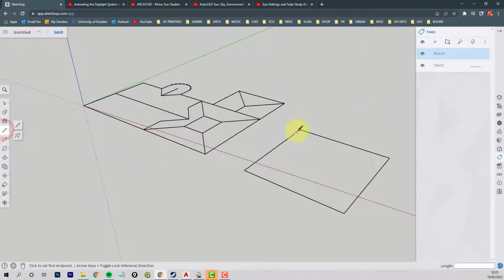Okay, I'm just going to trace around what we've got. I don't want it to snap onto SketchUp's own axes, so you can use the Alt key to stop it doing that. You don't have to hold it, you just have to press it. So you see there it says linear referencing all off. So I'm using the object snaps instead.